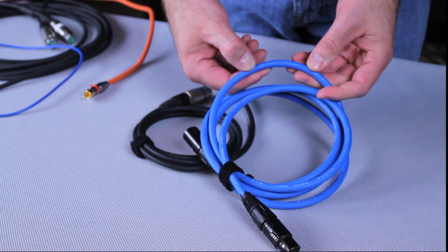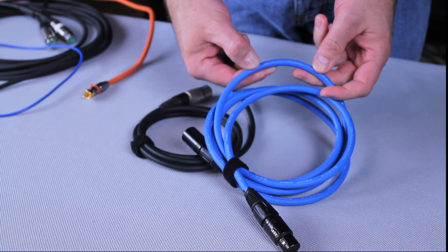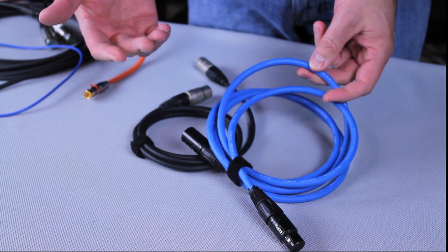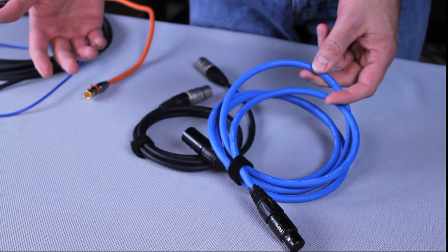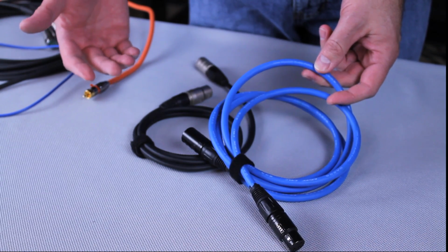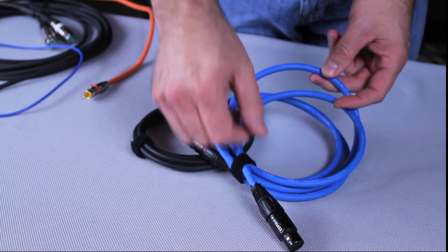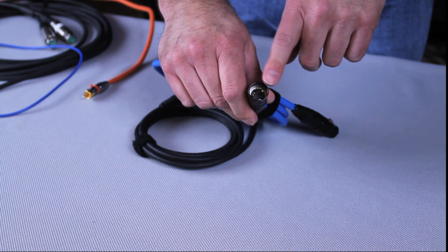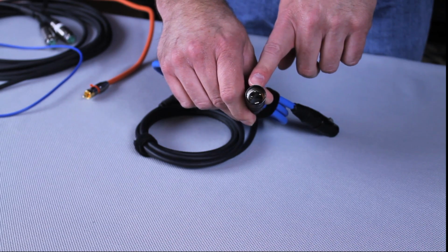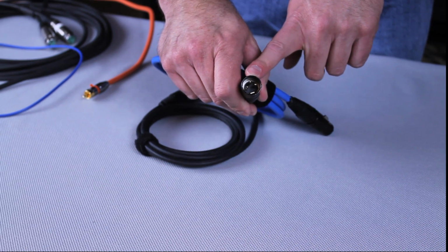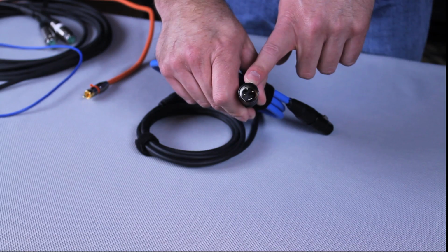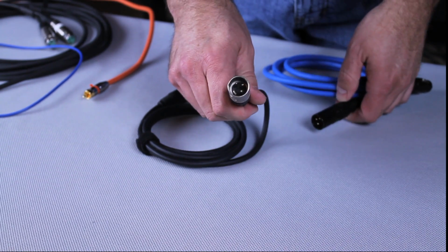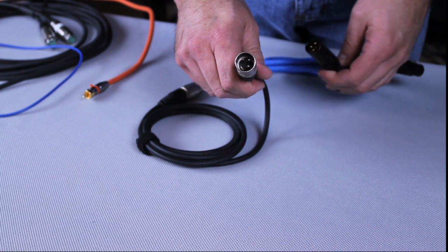110 ohm works well for AES digital. You can go down to 75 ohm as well. 75 ohm is basically the same as a digital video cable, video coax. But the secret is in the connectors. Remember we had hot, neutral, and positive. It works the same way, except with AES digital audio, you can actually get left and right down one of these cables. So it's like a stereo cable, versus in the analog world you would have to have two of these to carry the same kind of signal.